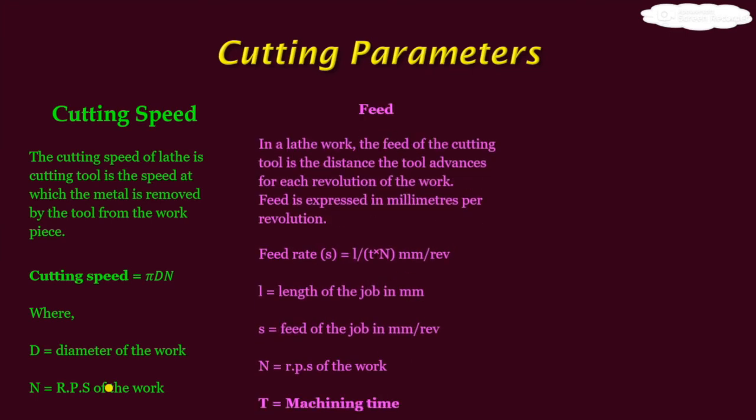The next one is feed. Okay, the job was rotating. Now, if the tool is stationary, then there is no progress of the cutting. So the tool has to move along the length of the job. That is the feed. Let's consider to move the total length of the job, it takes T time, where L is the length. Then L by T is the rate of feed.